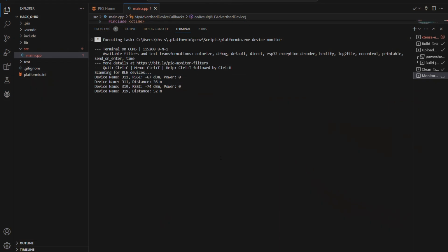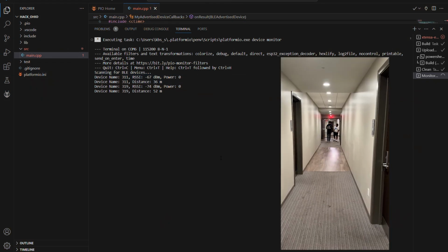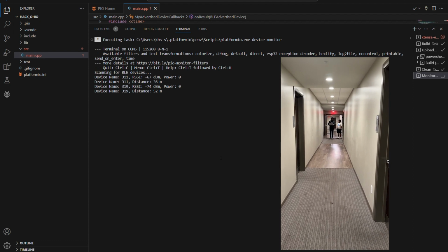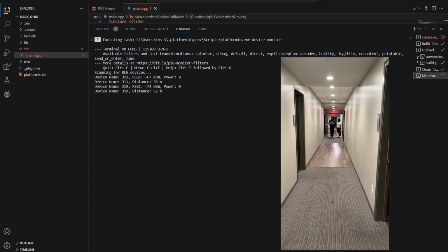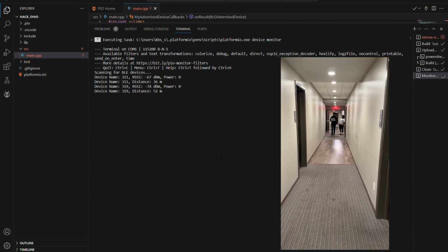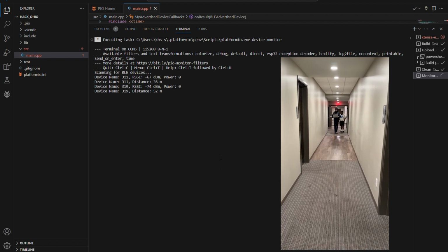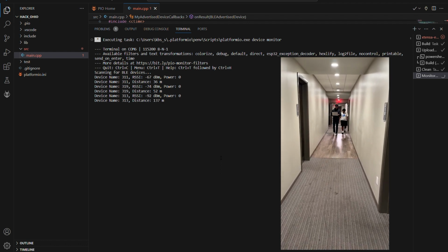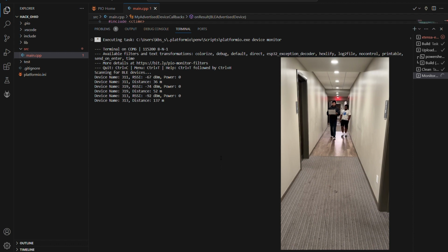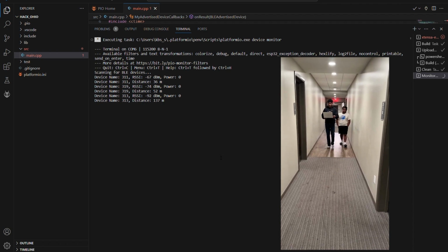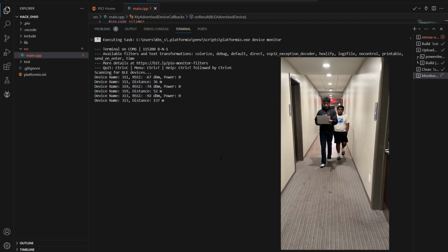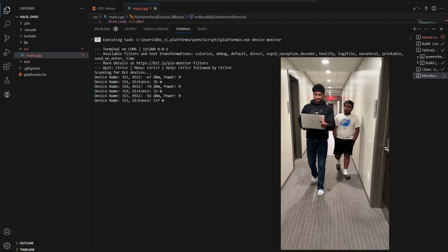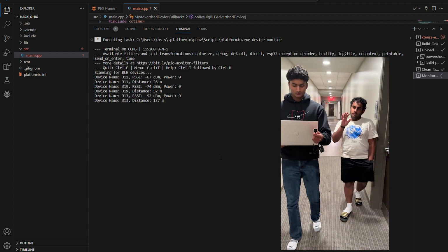BLE beacons can sometimes be found in existing infrastructure. In this example, we found beacons throughout an apartment complex as each of their locks utilized a Bluetooth device to unlock their door. The BLE beacon was sent as the room number and sent a signal strength as well. This allows for easier implementation as little hardware is required for future use. In the future, this can be implemented with Wi-Fi routers as they also transmit RSSI signals.